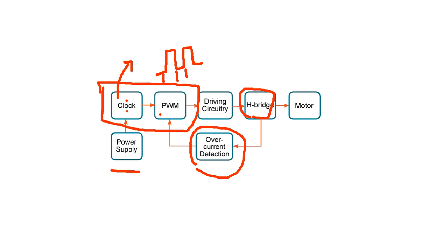Overcurrent detection means that if your current value increases or has an instantaneous peak, your circuit will generate a signal. Your microcontroller generates a signal. What does it mean? I measure the peak current value. For example, your maximum current value is 10. At one moment, your current sensor measures 20 ampere. Your microcontroller generates a trip signal. Your MOSFET will be disabled. Okay, this means overcurrent detection.